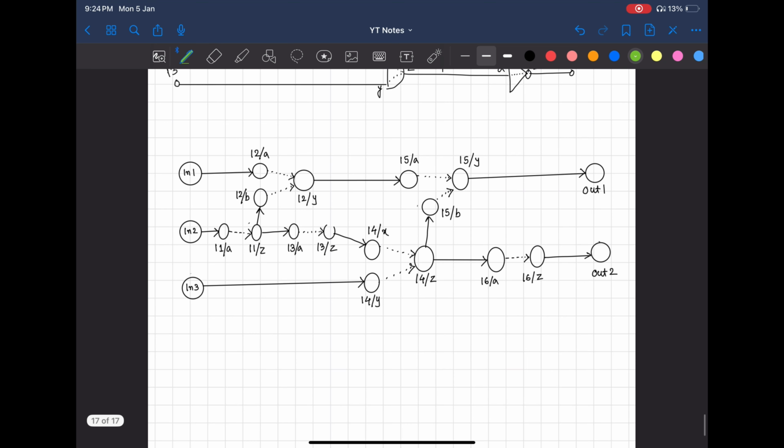So let's compute the arrival time. How to compute it? Take the source vertices as zero time, and take every net delay as 1. If you give 0, 1, then this point is also 1, this is 1, this is 2, this point is 3. Between 1 and 3 I take the maximum one.